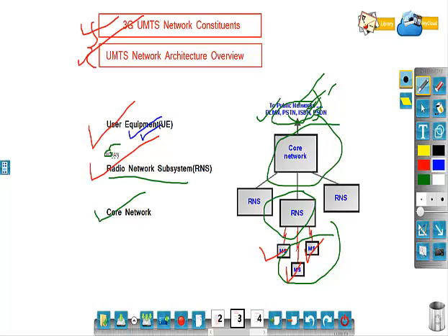The user equipment, or UE, is the major element of the overall 3G UMTS network architecture. It forms the final interface with the user, in view of the far greater number of applications and facilities that it can perform. The decision was made to call it a user equipment rather than a mobile. However, it is essentially a handset in the broadest terminology. Although having access to much higher speed data communication, it can be much more versatile, containing many more applications. It consists of a variety of different elements, including RF circuitry, processing, antenna, battery, and so on.